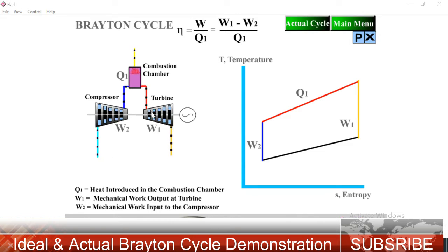Part of the turbine work developed is used to drive the compressor. An air standard analysis is used to study the open gas turbine engine, with the assumptions that air is the working ideal gas and the energy generated by the combustion is accomplished by a heat transfer source.